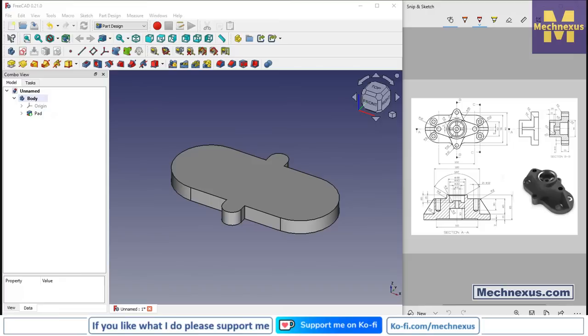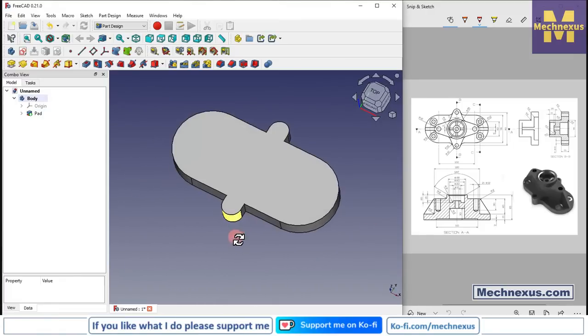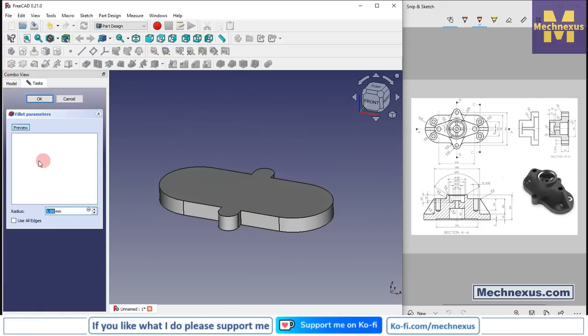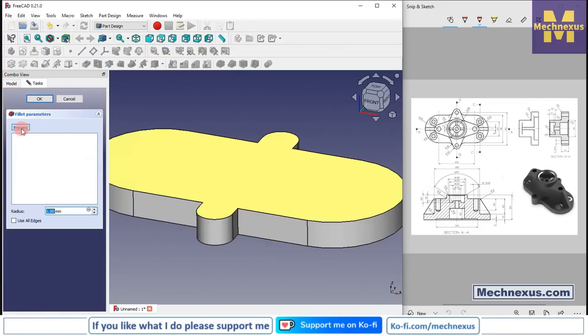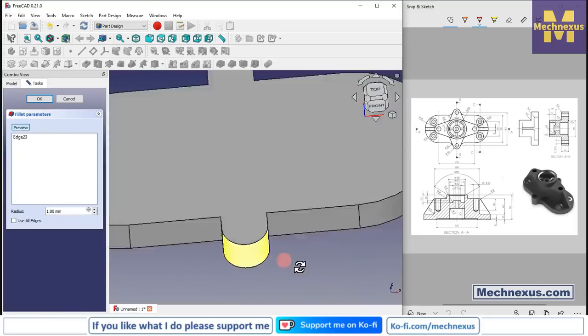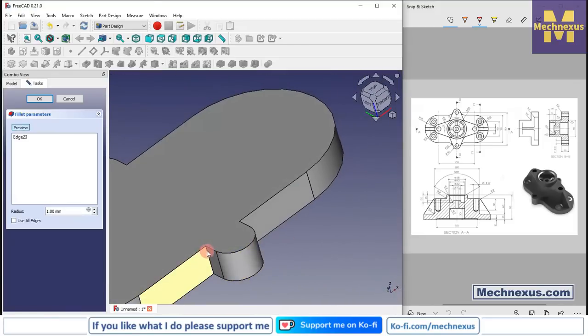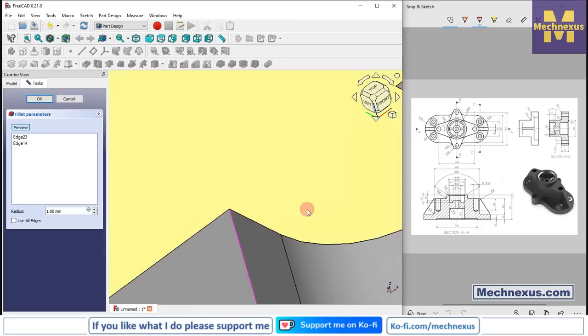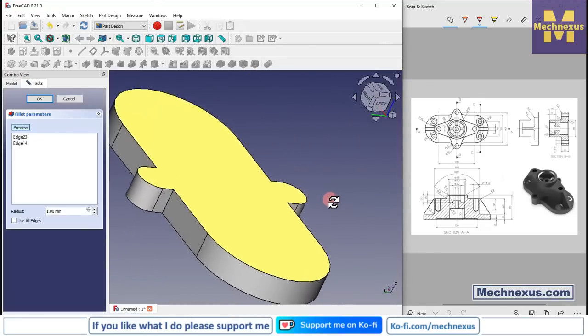And now we will provide the fillet to 4 corners, 2 on the front side and 2 on the back side. So we will select the fillet and we will select this edge, press the control key and create an edge selection.